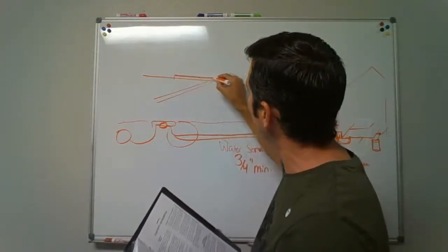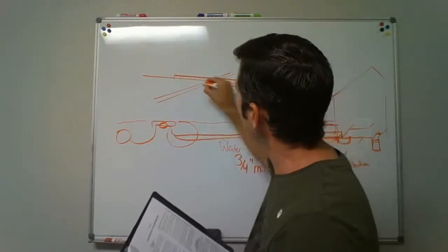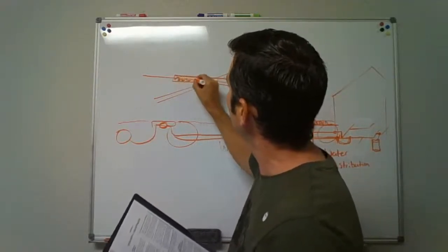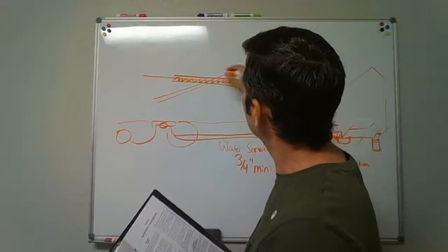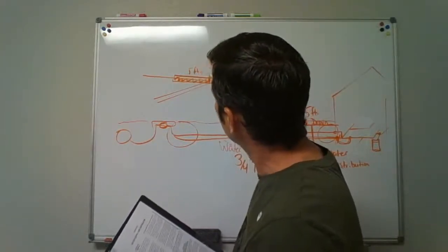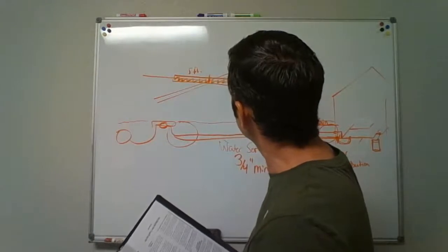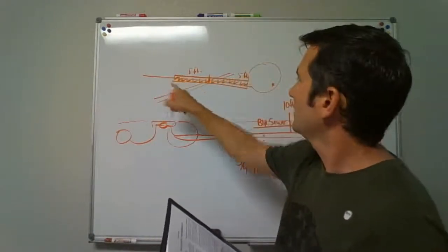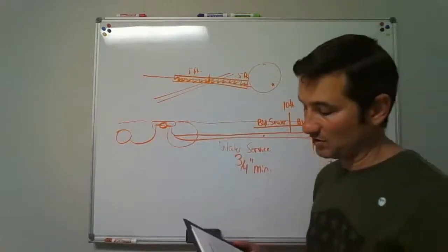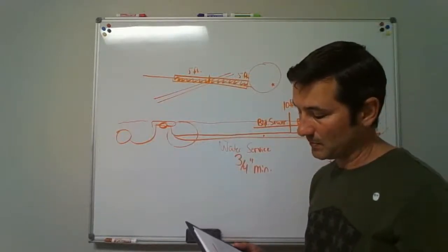You've got to put the pipe in a sleeve, and it's got to be a 10-foot stick of pipe, so that from the center line where it passes through, you've got 5 foot on that side and 5 feet on this side of sleeving that water line when you cross your sewer, if the sewer's not of approved material.